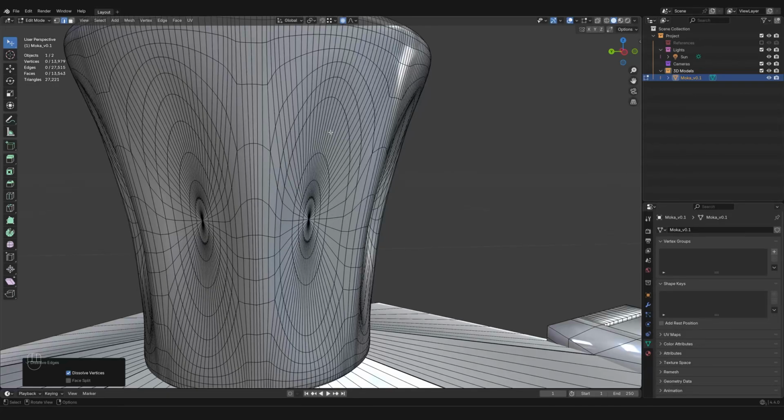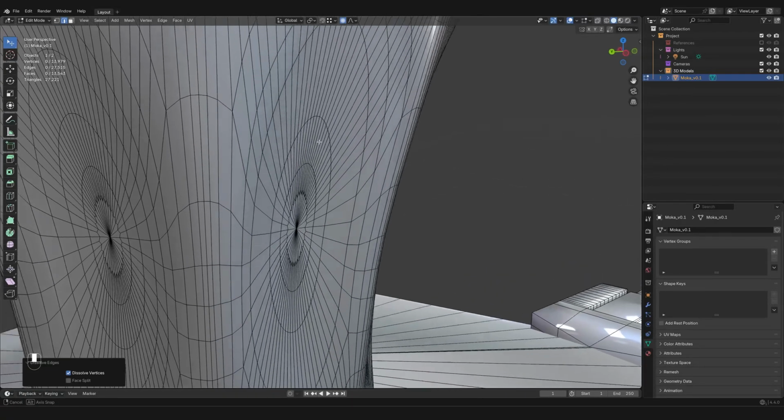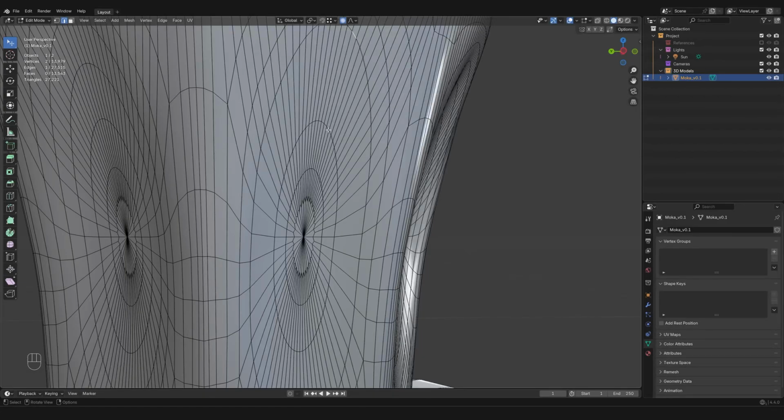It's like a merge operation that makes it so that this surface gets recreated using the two neighbors. And now, all along where we had the edge loop, we have a clean set of faces that are just flat between this edge loop and this edge loop.